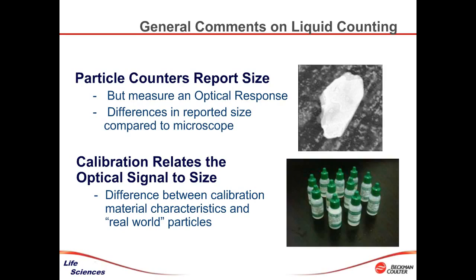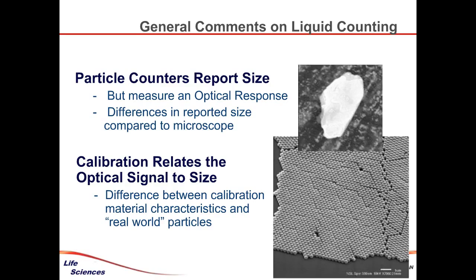We use calibration material that is commercially available and traceable to national organizations. In the case of the United States, we talk about them as being traceable to NIST, which is the National Institute of Standards and Technology. And these are very, very beautiful, precise microspheres. And so we have a quantity of those. We certainly are looking for consistency in size. We introduce that to the machine. We record the response. And that becomes a calibration based on multiple introductions of sizes. So we create a calibration curve or response curve over a range of sizes of interest or the instrument's capability. Again, for light obscuration, that's typically something on the order of 1 micron up to 3, 4, 500, 600 microns.